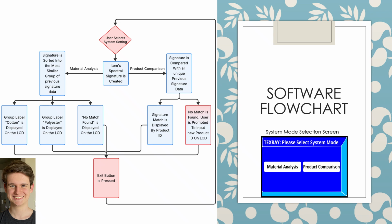Once the user has their sample in place, their interaction with the system begins by selecting a setting through the LCD screen. The two settings are titled Material Analysis and Product Comparison. Selecting the former will return the identified material of the current sample to the LCD screen, while the latter returns whether or not the current clothing item has already been scanned and stored. In product comparison, if a match for the clothing item is found in prior scans, then the ID label of the match is displayed, whereas if no match is found, then the user is prompted to input an ID label for the new clothing item.